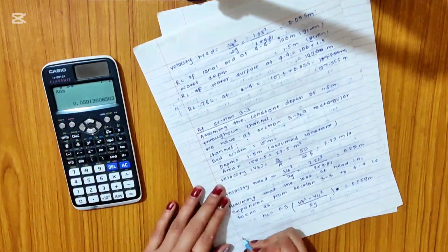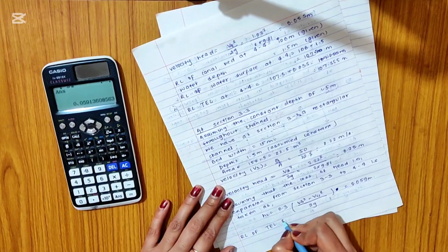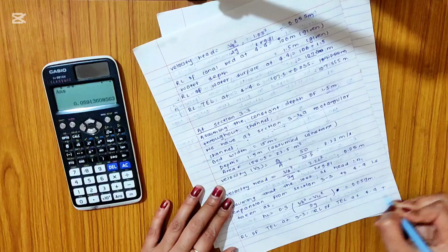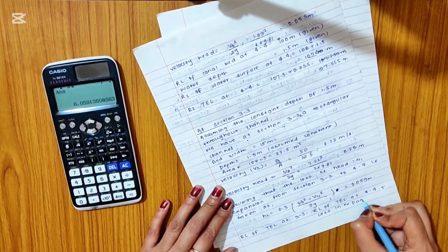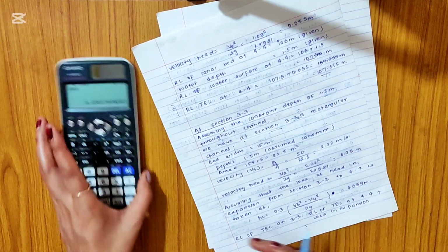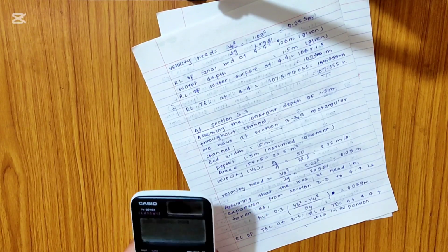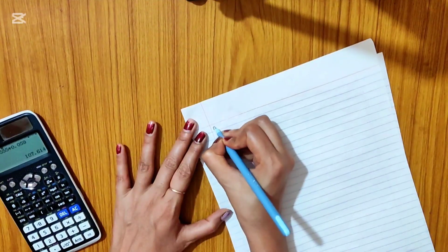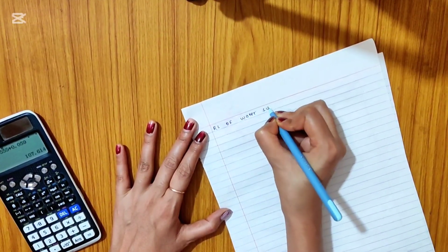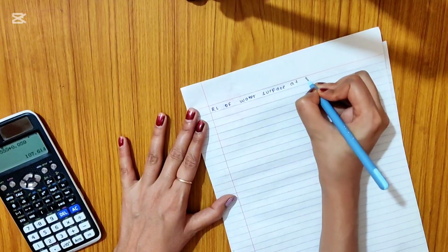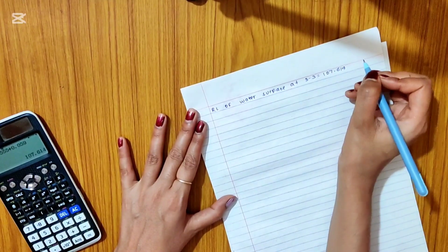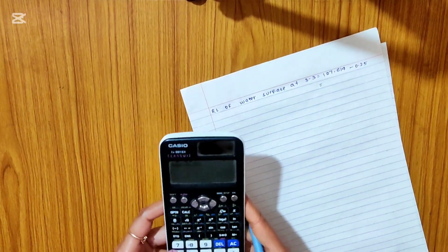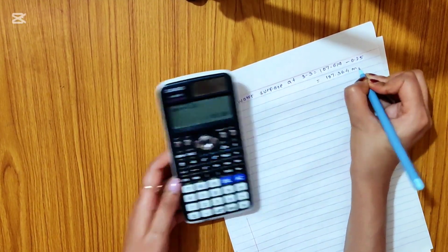0.059 meter. So now the RL of the TEL, total energy line, at 3 is equal to the RL of TEL at 4 plus the loss in expansion, that will be 107.555 plus 0.059, which is equal to 107.614 meter. Now the RL of the water surface at section 3 is equal to 107.614, which is the RL of TEL at 3, minus 0.25, which is the velocity head, which is equal to 107.364 meter.